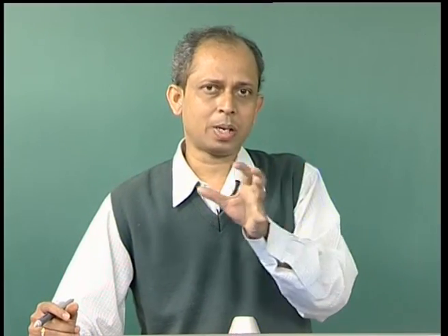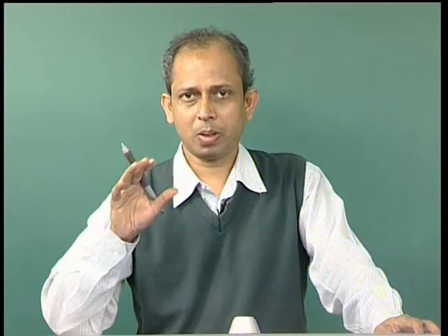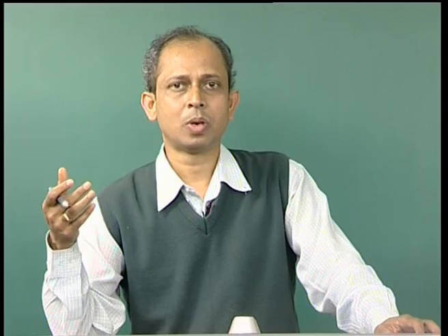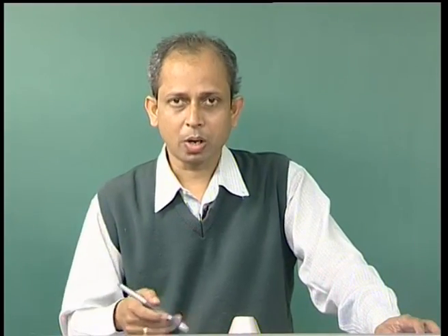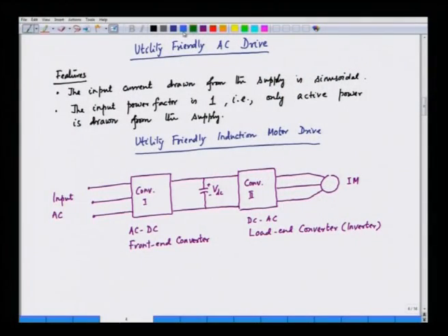Now, the control of these two converters is somewhat independent of each other. The load end converter is controlled in a given control scheme, which could be a simple V by F control, it could be vector control, or it could be direct control, to ensure good performance of the induction motor.